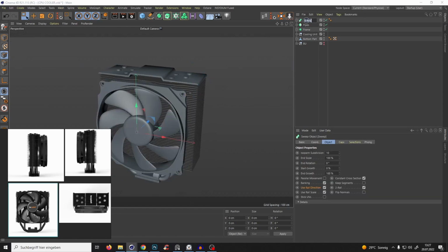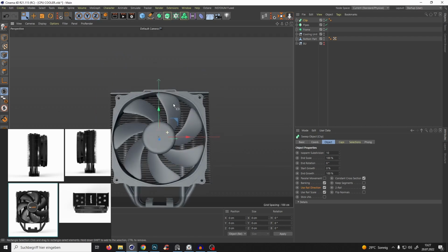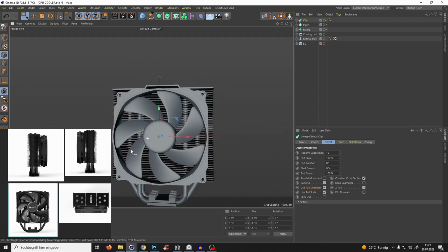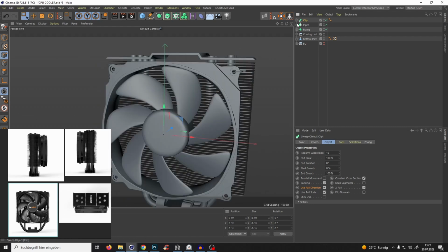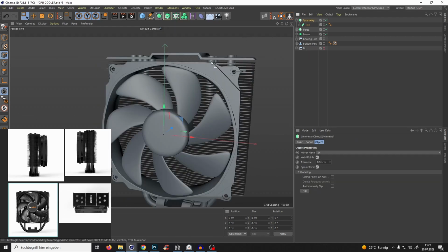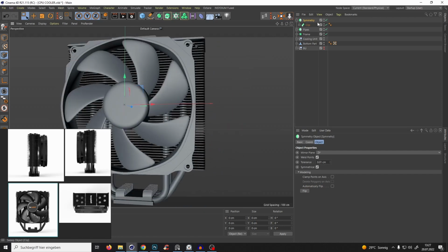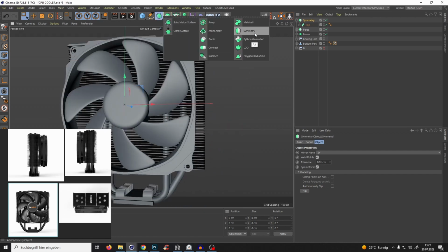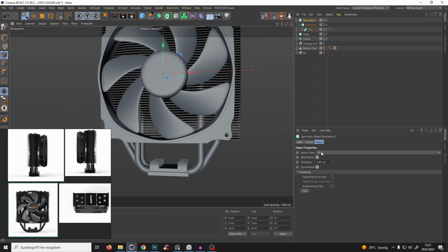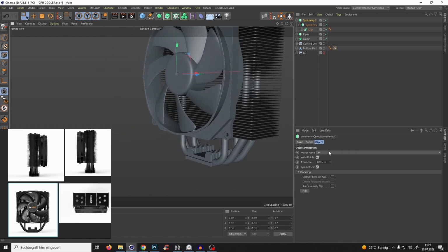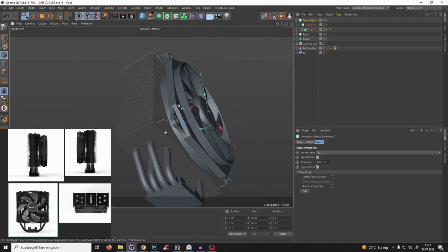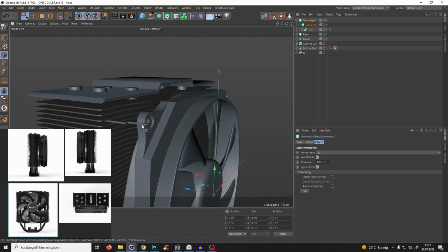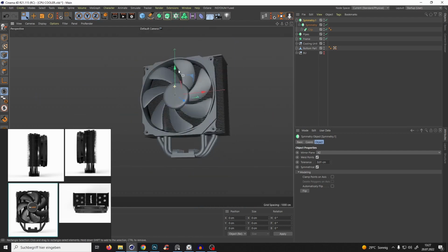So I have here a clip or something, and you see this clip, the axis is exactly in the middle of where we want it. So we can just take the clip and just, again, symmetry. So we have it over here, and again, symmetry with alt click and symmetry, and mirror plane XY or XZ. So we have, you see, on every hole our thing here. That looks very good in my opinion.